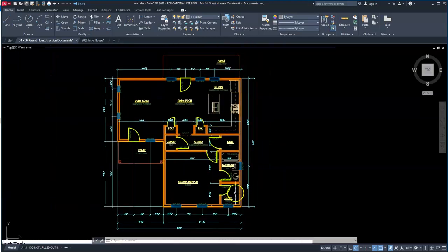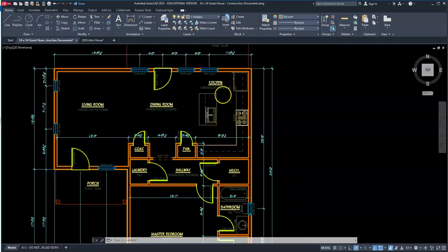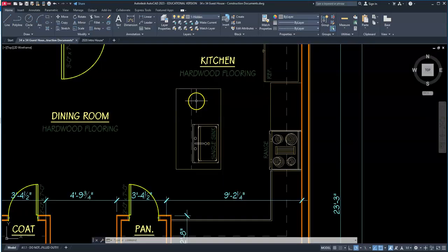Okay, so again, anything above 4'6" is shown as hidden, with the exception of this cabinet line here, because this is below a surface and the surface is inside or below the 4'6" line, but it's still being obstructed. We can't see it cleanly, so it is indeed hidden as well. So we've got two of those things going on at the same time.